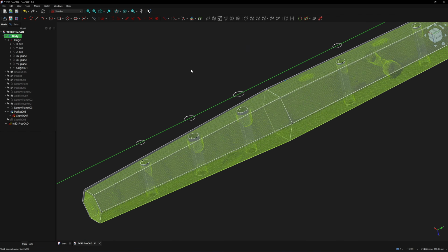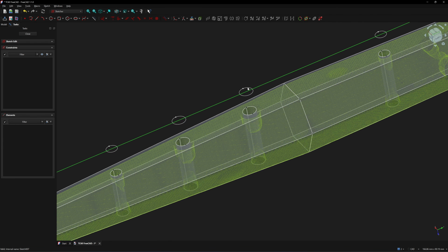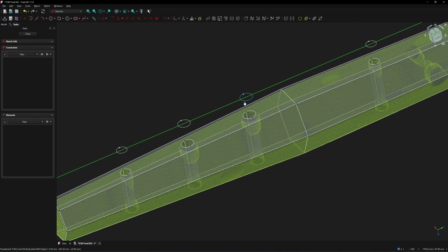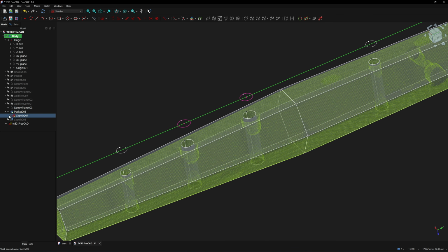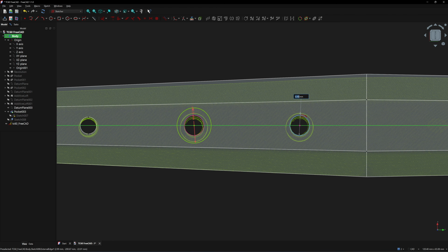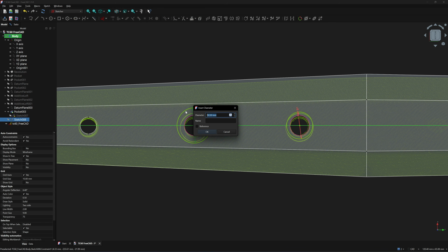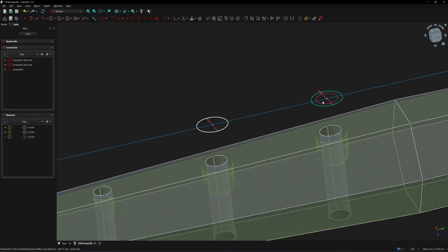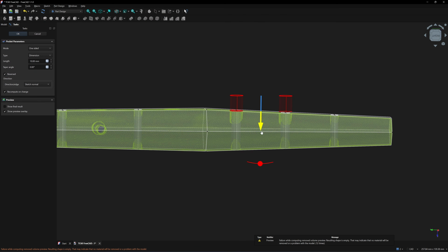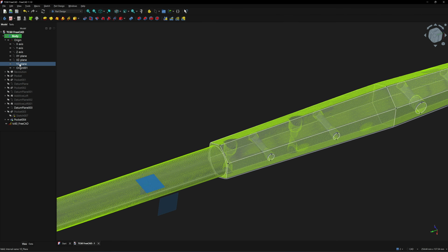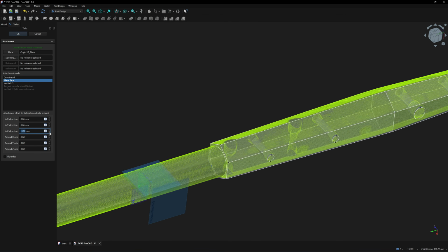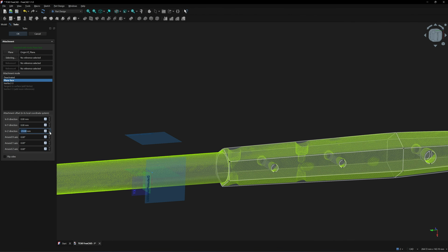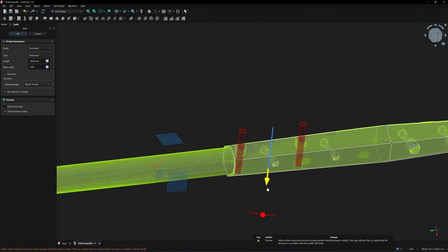On the same datum plane, create a new sketch. Right-click, use external projection, then select the reference circles. Create two circles for the counterbore with an 8 mm diameter. Delete the reference sketch, then use the pocket command to cut them to the required depth. On the YZ plane, create a datum plane and move it above the cutting hole. Then repeat the same hole cutting process.